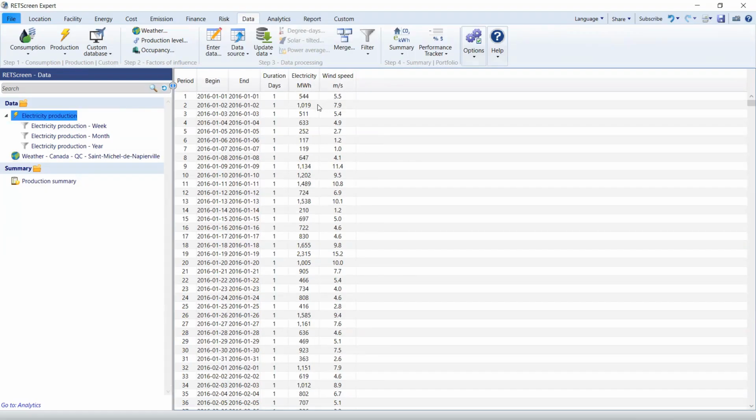So if we see the electricity production going up and down, that could be indicative of a problem with our project. If we see, for example, the electricity production drop down from one day to the next, it could simply indicate that the wind was less strong that day. So in order to assess whether there is some underlying problem or deterioration in our wind farm, we really have to remove the impact of the changing wind speed.